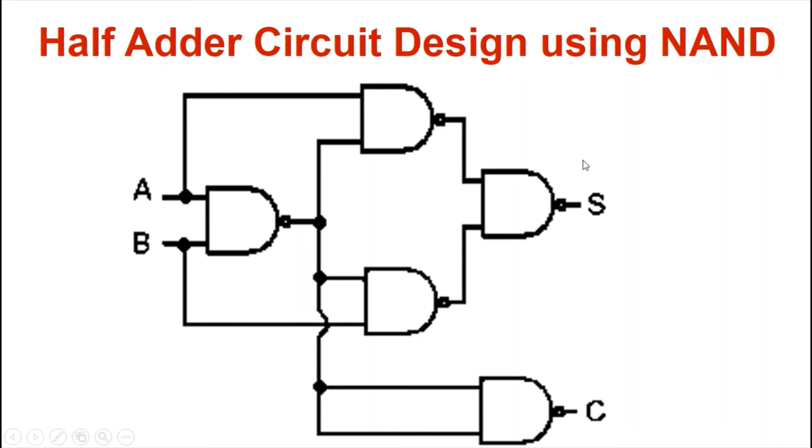And finally, we take one more NAND gate to get the output as the sum. This final NAND gate has inputs from the outputs of the previous NAND gates. And to implement the behavior of the carry, the output of the first NAND gate itself is connected to both the inputs of another NAND gate, and that NAND gate will ultimately give us the behavior of the carry.